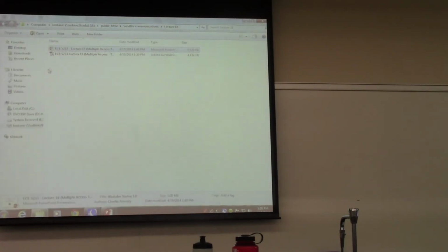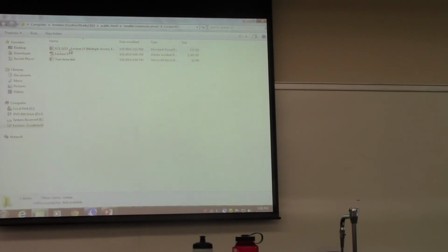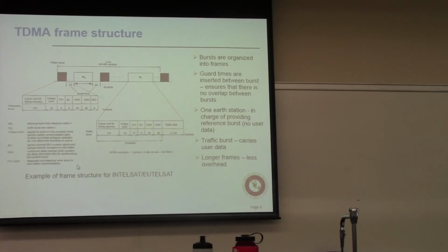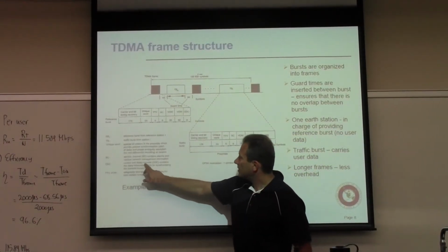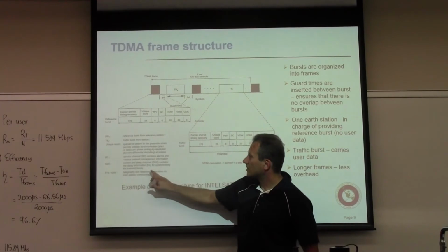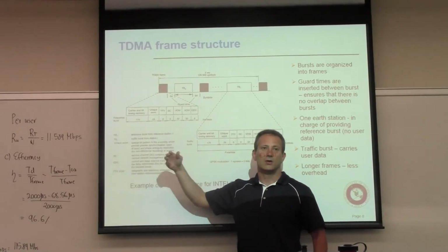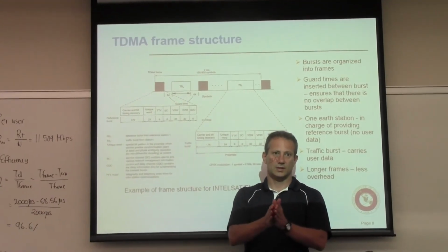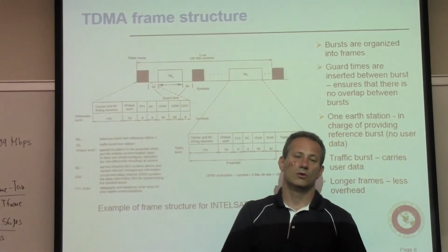I think it was in lecture 17. I said I was going to go back to it. CDC, the control and delay channel, contains the delay information for synchronizing the transmit bursts, right? So there is a constant feedback that goes through this channel on where the preamble actually arrives within the allocated time slot, right? And that allows you to recalibrate on an ongoing basis.